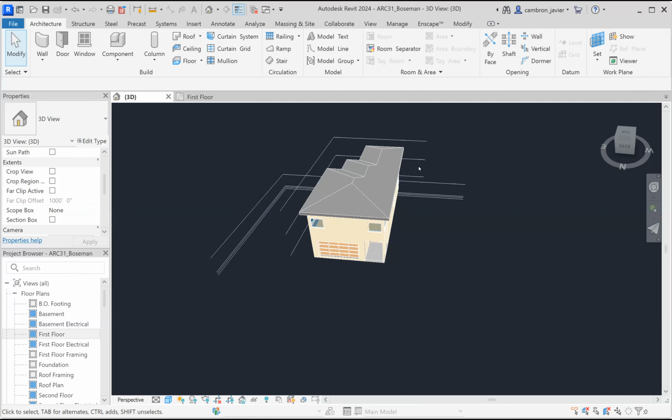And in the real world, when you actually get a surveyor to provide the three-dimensional topo surface, we're still going to have to edit the topo surface regardless, because we're going to be adding or making changes or building a new building, which is going to require us to manipulate the topo surface. And so manipulating an existing topo surface is very similar to creating our own. So that's where we're going to go about it in this lecture.